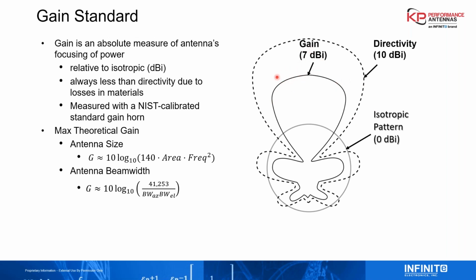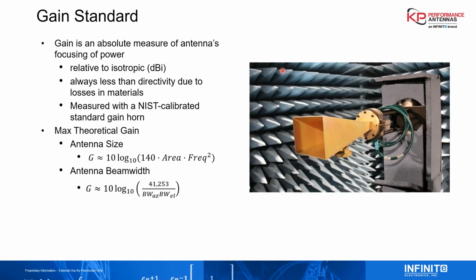Now, to measure gain, you have to use a NIST calibrated standard gain horn, but there are other ways to measure gain that are not as accurate. This is the most accurate way.